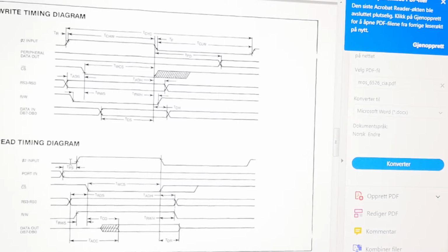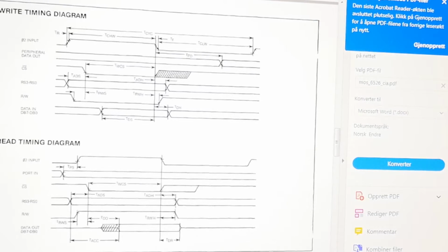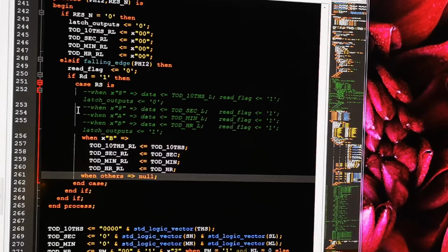So this never was true whenever we had a rising edge here. But on a falling edge, we did have a chip select. So that's why it's working now. The strange thing is that I tested this last night and it didn't work.